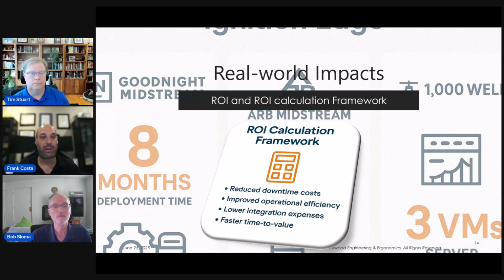All the other work is taken care of: the publishing to the broker, the visualizations, because in this case we're using Ignition Gateway and Ignition Edge. In the initial architecture, I'm not looking to see machine one, torque gun one value. When you start using tools like UNS and CDM, I'm just looking at: give me everything that's an attribute, give me everything that's a set point, give me everything that's metadata. And all those visualizations are tagged not to the individual signals, but to those UNS groups.